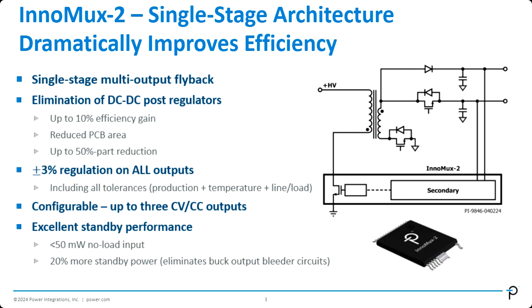Unfortunately, I can't do isolation between the different outputs over here because, as you can see, we share the SR here, and all the current goes through the SR. And I sense the information going past the SR. So they really kind of need to share the same ground. So unfortunately, I can't do isolated outputs on the secondary side.